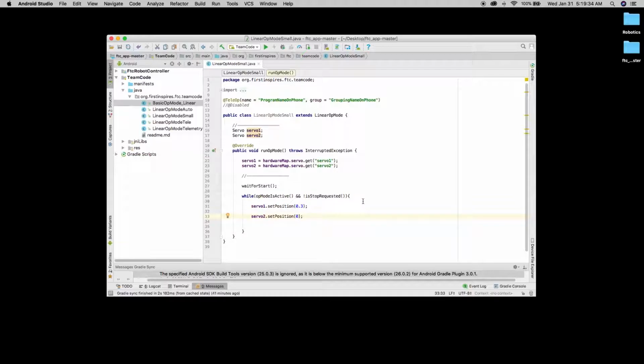So in a continuous servo, these values are a little bit different now. Since it can go on forever, it's more like a motor than it is a servo anymore. However, it does not go negative. So there's 0, 0.5, and 1. Those are the values you have to worry about.